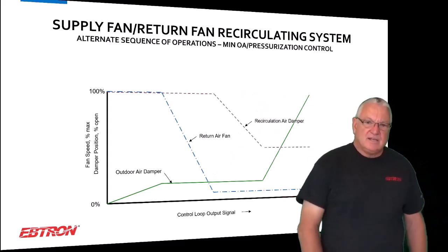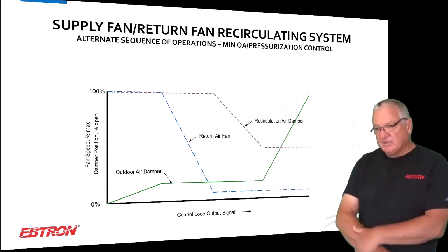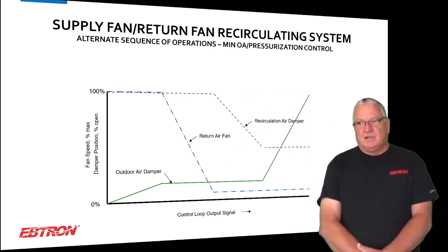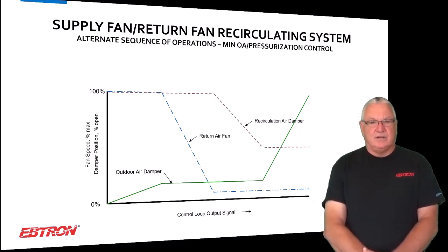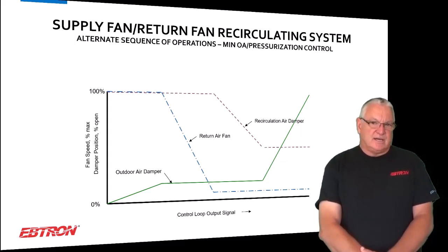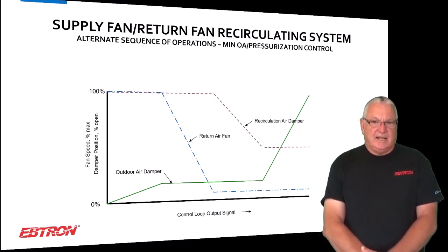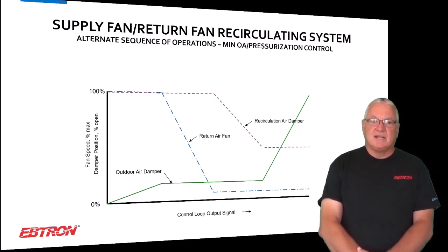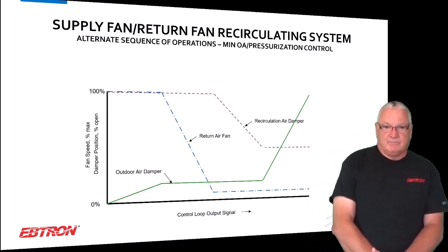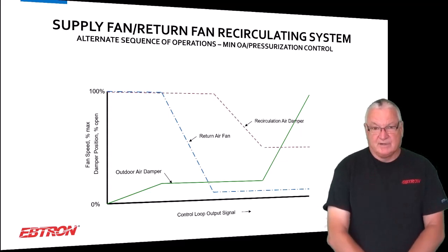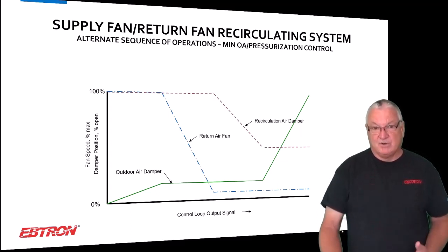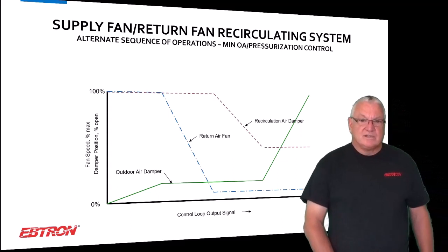An alternate to this would be, I have a really oversized outside air damper. I can't make this really work, and I want to do this a little differently, okay? And I learned about this a long time ago. Dr. Stanley Muma was looking at doing, Penn State was looking at doing outside air control, and he was modulating the recirculation air damper because outside air dampers were so bad and so big and so hard to control. And this works out pretty well too.